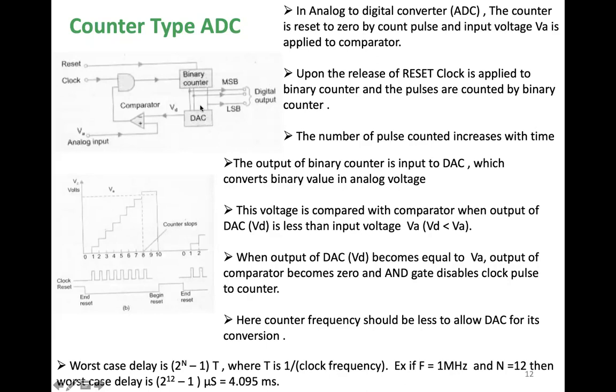Before it converts, if it sends the other value, then what is going to happen? We are not going to get the previous value, it is lost. So we have to wait for the previous value, and then it gets into the comparator. It checks for the differences. If there are differences, it's going to be 1. If there are no differences, it's going to be 0, and 0 comes here. It's an AND gate, so irrespective of whatever clock you're giving, the binary counter stops.